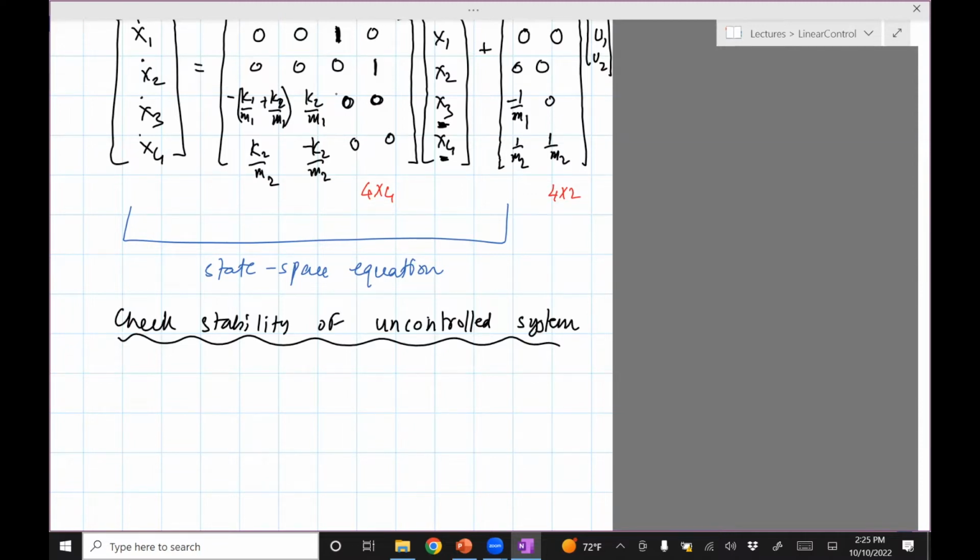And the way you can check stability, just like we did for the walker going downhill, is that if the walker is on that cycle which is stable, if you keep walking, it does not fall down. But if you perturb it and it falls down, then you know it's unstable. Or if it doesn't fall down, it's stable. So in order to test the stability, you need to push the system somehow.